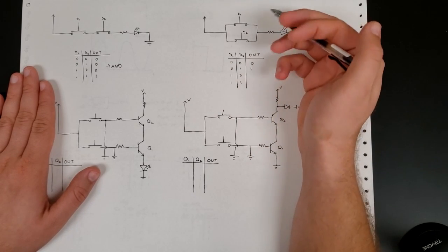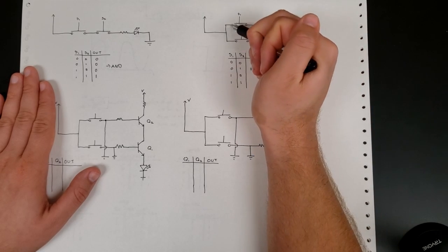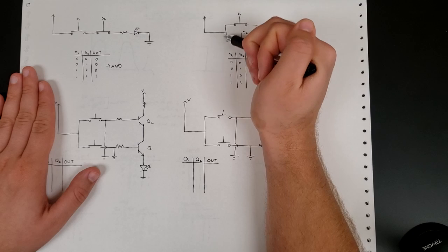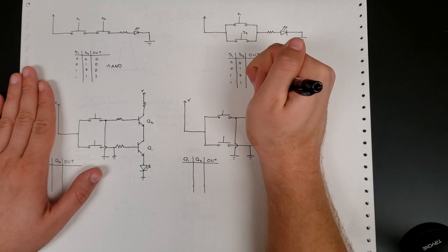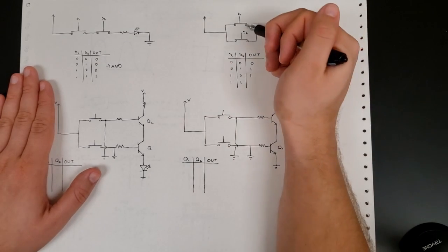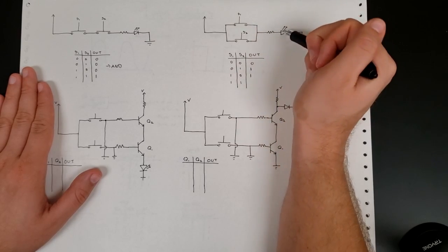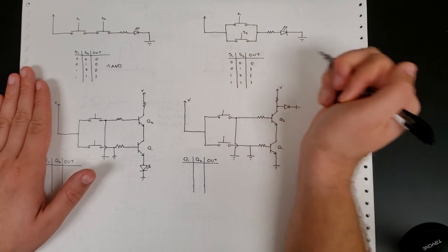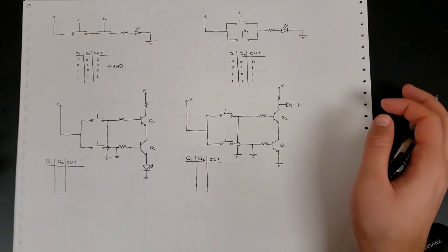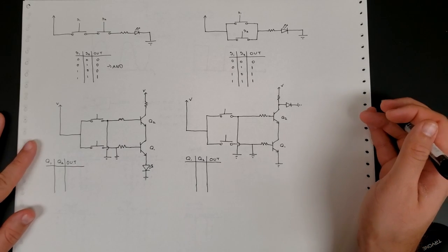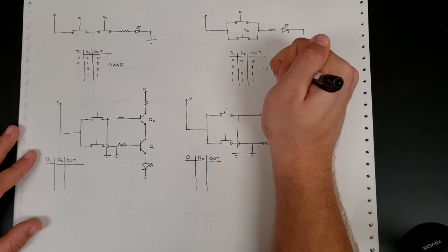Now the same is true vice versa, right? If S2 is now open and S1 is now closed, that means my current can now flow through this top branch of my parallel circuit. It can flow through S1, which means I'm going to get some current flowing through my LED, which means I'm going to have an output. And now if they're both closed, right, same thing, I still have a closed circuit. Current can flow through this LED if they're both closed, and so again I will get an output 1. And then again, referring to either your manual or the video, or earlier in the video where we did those truth tables, if you look at this output, you can see that this corresponds to an OR gate.